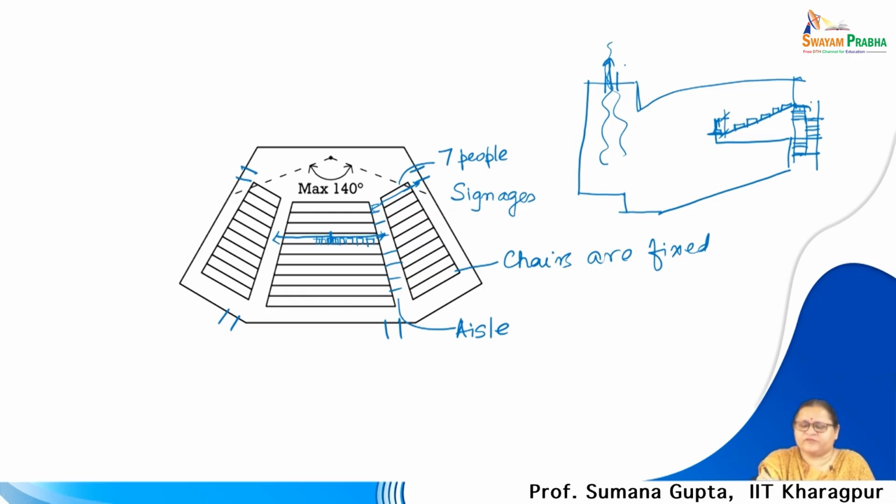So, in case of fire, the people should be ready to come out and take exit. This is the auditorium space. So, this will be the foyer space, and there may be staircases in these locations to go up to these balcony levels. So, no canteen, no storage should be encroaching these exit areas, these routes for exit.